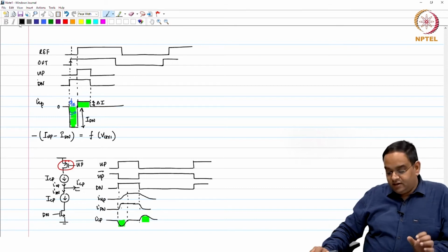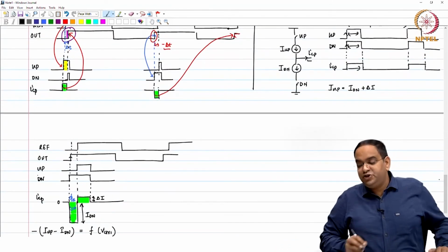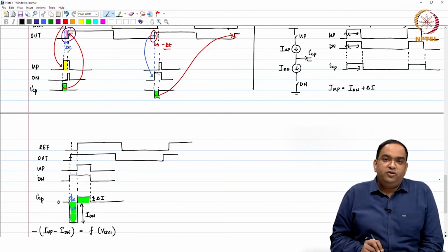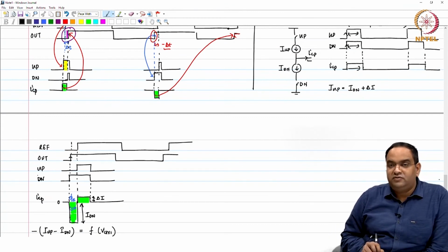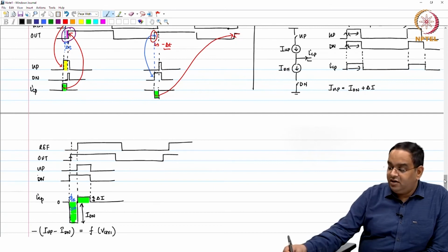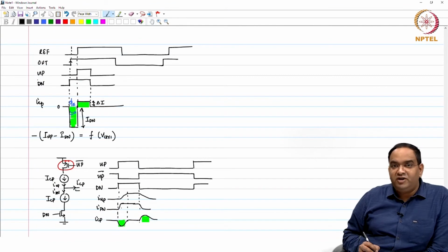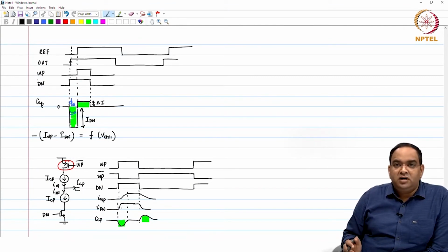which is again a nonlinearity. All these charge pump related issues, whether it is the static difference between I up and I down, or the dynamic difference based on the control voltage, or the different response time of NMOS and PMOS, add error to the control voltage.